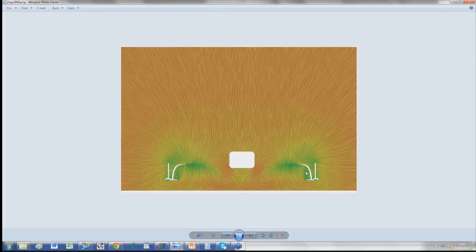That means that the velocity in front of the tire is reduced, and that will reduce the pressure that is applied on the tire, so the drag will reduce. This is one of the main things that you do at the beginning. You can see that this car hasn't been developed enough, simply because it's the very beginning of the project. But we know that we need to develop this area so that this vortex will get bigger and bigger until it bursts, and the drag will reduce on the car.